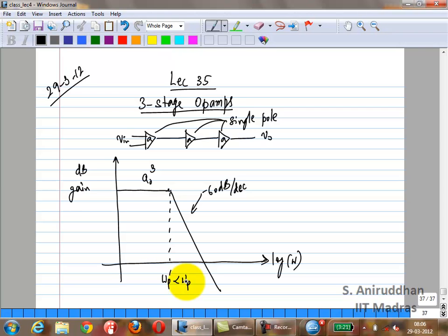Okay, so then what will you do? If you had to rearrange things, what would you do? Knowing what you know about op-amps, gains, poles. No, so you have 3 stages, right? How would you apportion the gains? So right now I have assumed equal gains and equal poles. If you didn't have that restriction, what would you do?